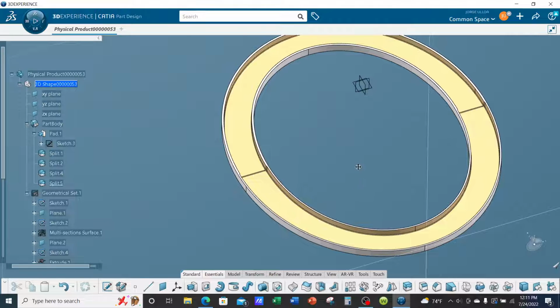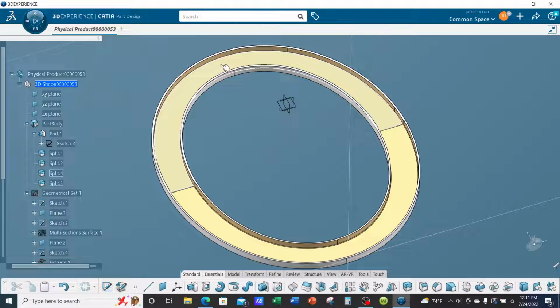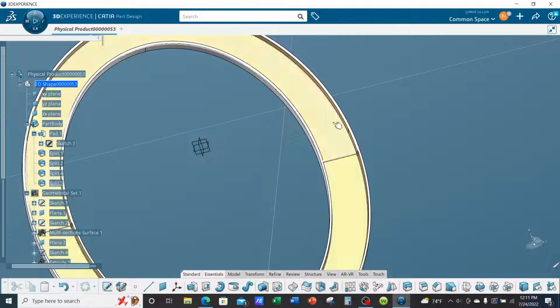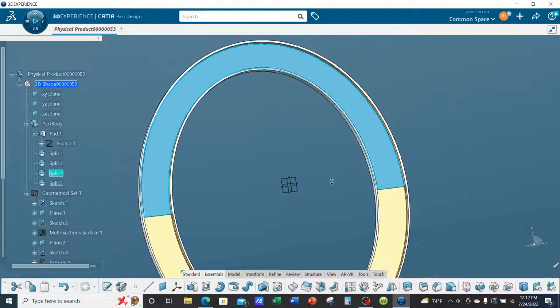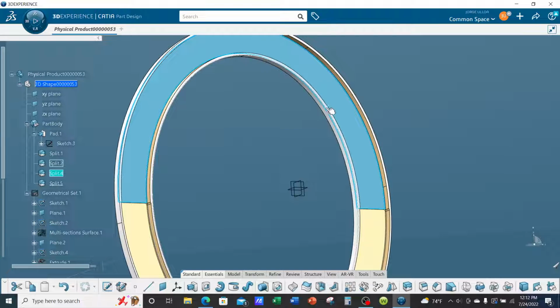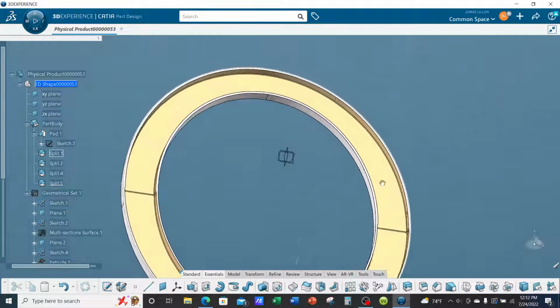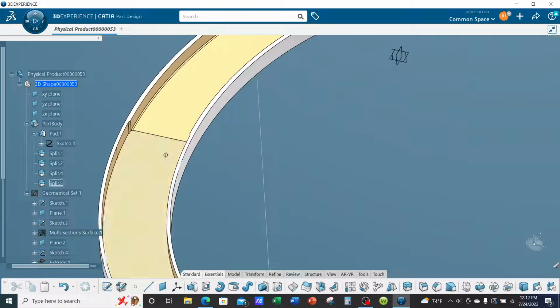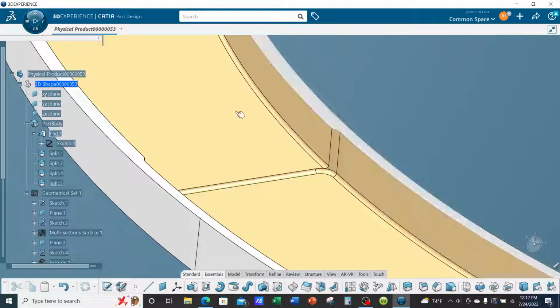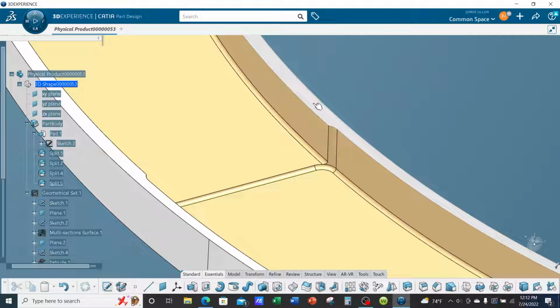Okay, so once again, let's go over this one more time. We have a thickness on the upper portion of the frame at 1/2 inch. Same thing with the flanges. Flanges have a thickness of 1/2 inch. Typically they're not the same, one may be thicker than the other. But just to keep this exercise simple, I kept it the same. And then on the bottom portion, you can see how it goes from a 1/2 inch web to 3/8, 0.375 inches.